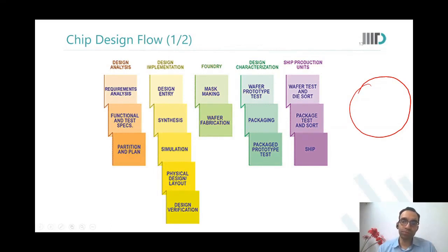So we are testing the good ones twice, effectively. Yes. As I said, at every step there could be some failures. On the wafer, you saw that out of 1000 dies, 990 are working, so you package those 990. After packaging, out of those 990, 980 may be working, and only those 980 you send to the customer.